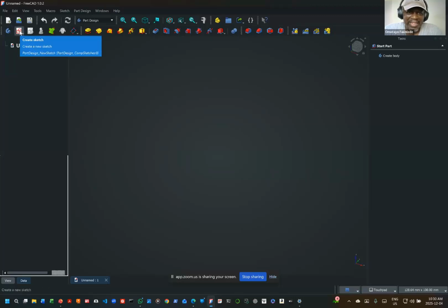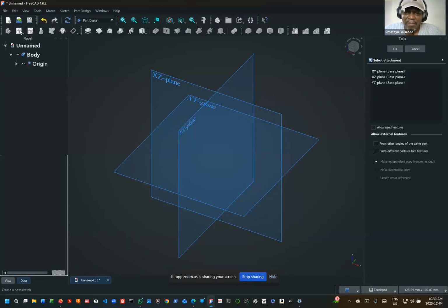And if you loiter near the sketcher, it says create sketch. So that is what's going to happen there. So you click that and it says create, and immediately you are given 3 planes. Somebody has asked, how do I know which plane to use? Well, you are going to get that by experience. Many times it doesn't really matter.